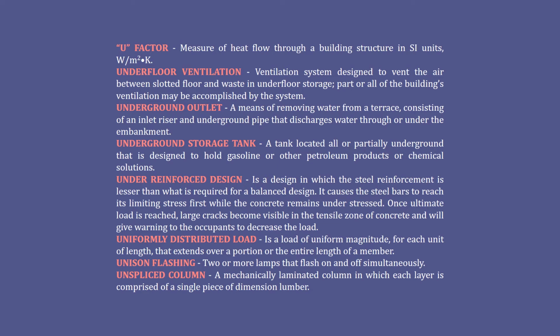Underground storage tank. A tank located all or partially underground that is designed to hold gasoline or other petroleum products or chemical solutions. Under-reinforced design is a design in which the steel reinforcement is lesser than what is required for a balanced design. It causes the steel bars to reach its limiting stress first while the concrete remains understressed. Once ultimate load is reached, large cracks become visible in the tensile zone of concrete and will give warning to the occupants to decrease the load.